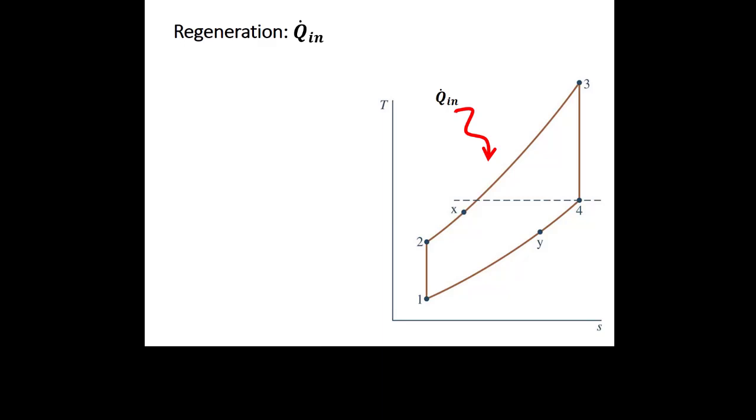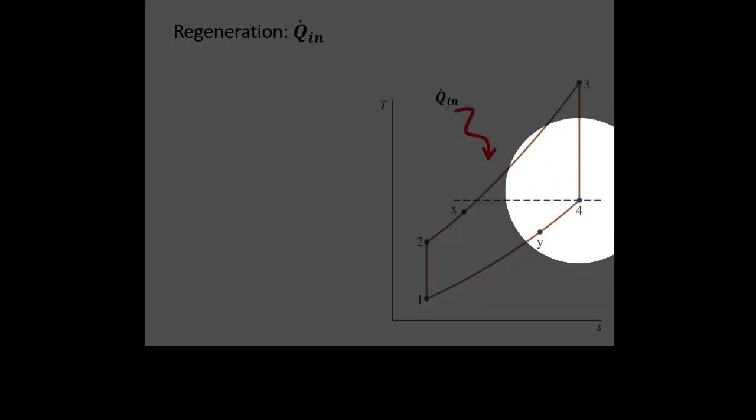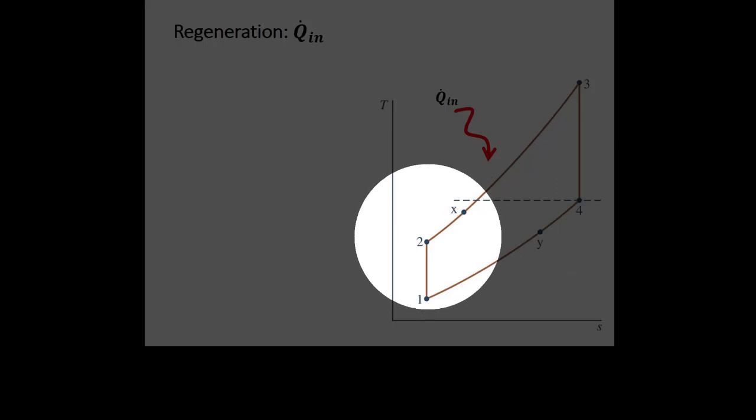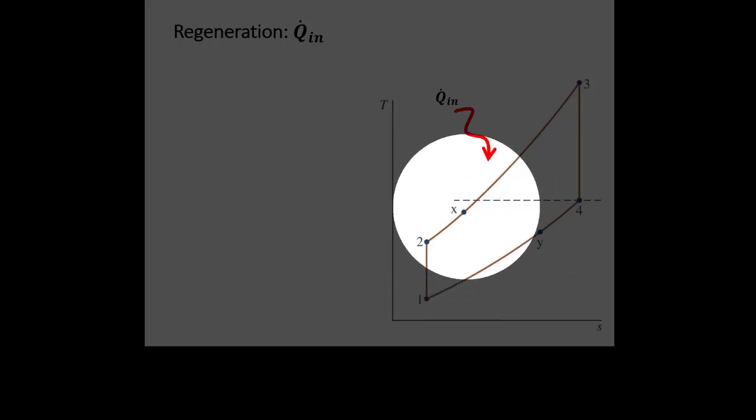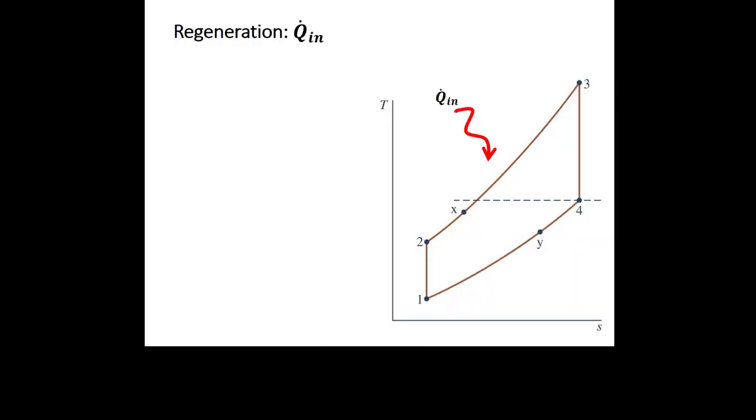So this is the same thing. We have this exhaust temperature that comes out of my turbine. And I can preheat the fluid that comes out of the compressor before it goes into the combustor, but never past the temperature of the exhaust gas, because it's kind of like the temperature inside the oven. Right? We can't get past that. And actually, we don't get quite as far as that temperature.